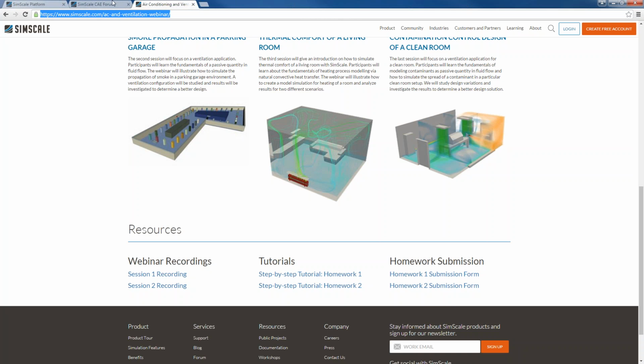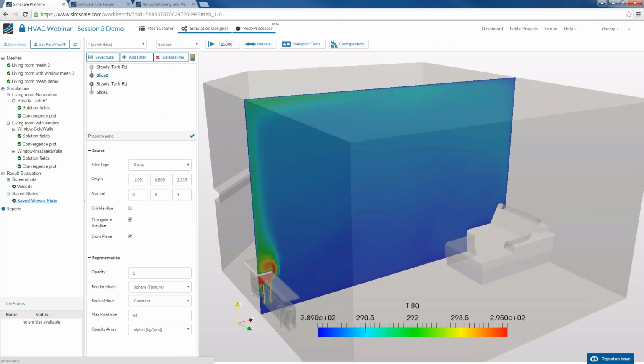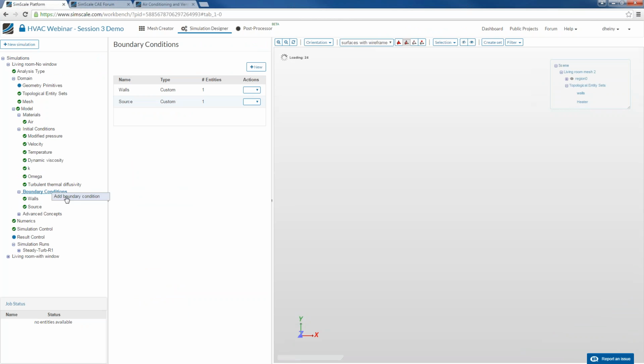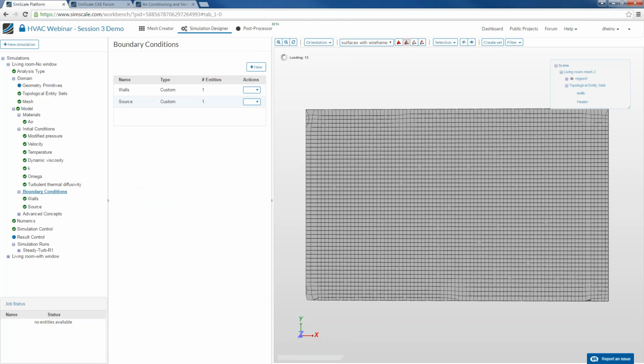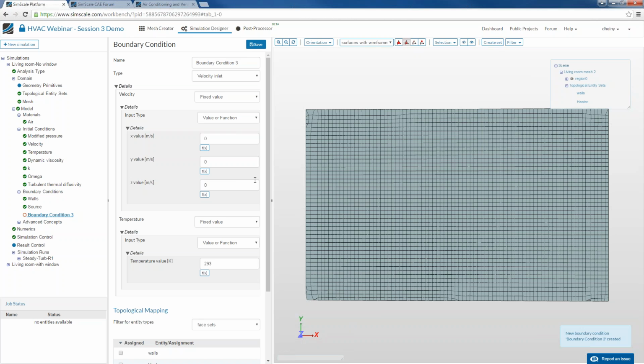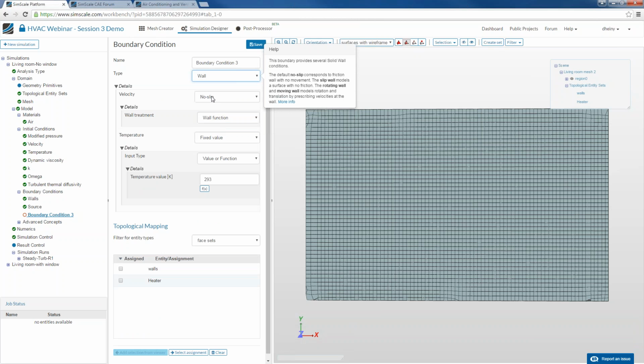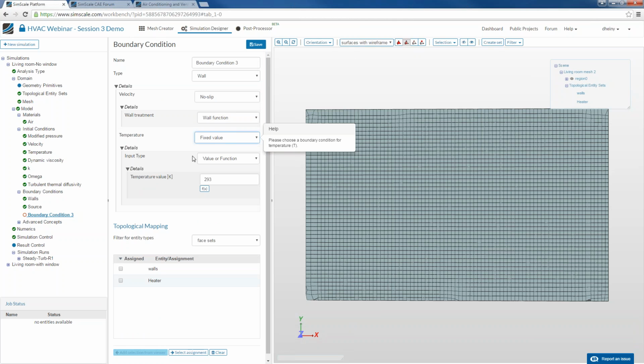I see. Good question. One user asks, let's go back to boundary conditions. One important aspect, very good question. One user asks, because I chose the custom boundary condition, but we could have also said, okay, why not simply use the wall, put it to wall slip, and then have a fixed value. So let's call this simply a sort of source 2. So we model the radiator or the heating, the heater at 40 degrees Celsius, right?